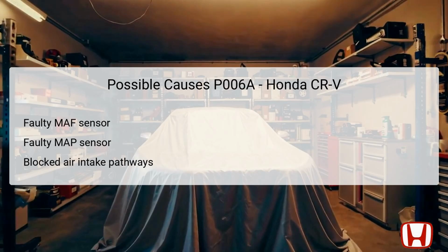These blockages could stem from damaged air ducts, debris in the intake system, or issues related to the air cleaner element. Each of these problems alters the air supply, leading to performance issues and triggering the DTC. Hence, all potential causes must be thoroughly investigated during the troubleshooting process.